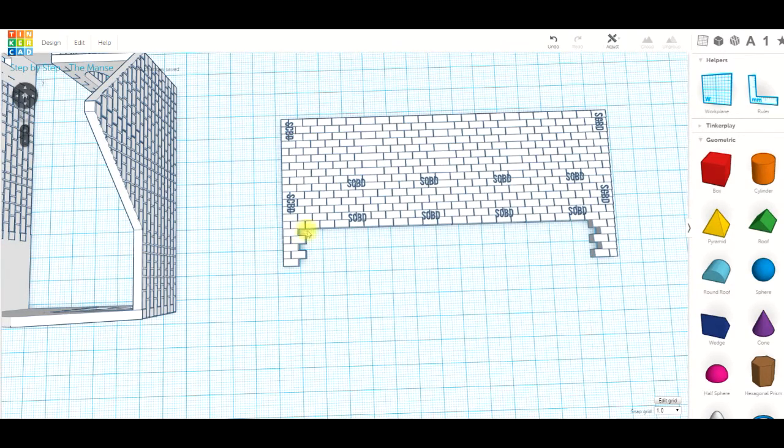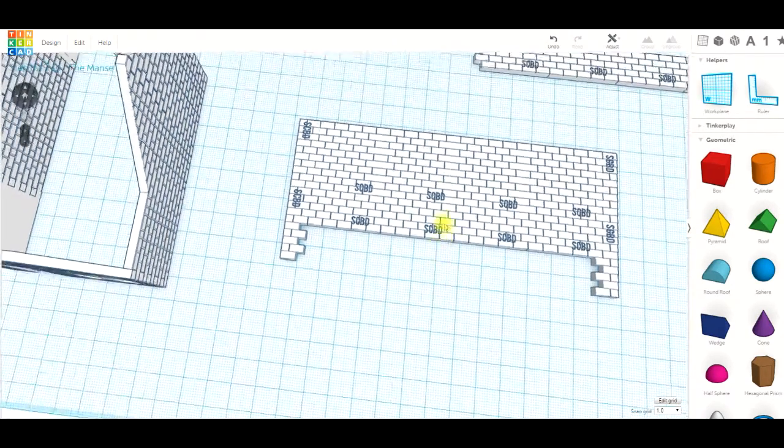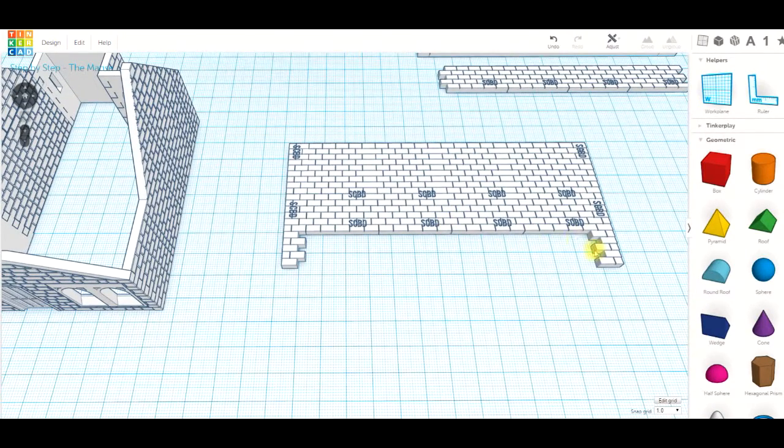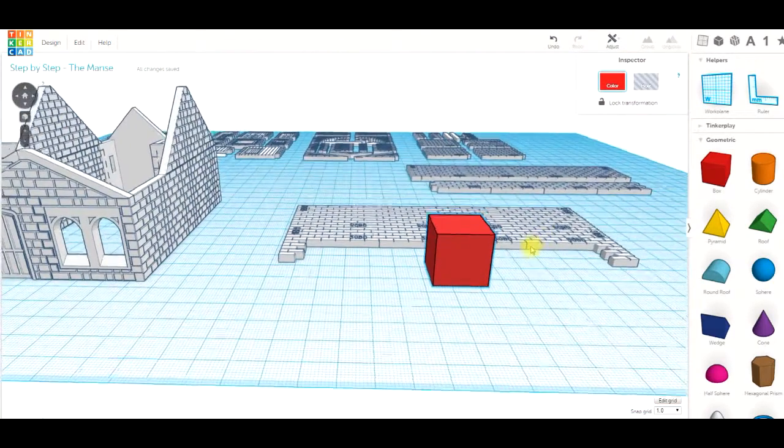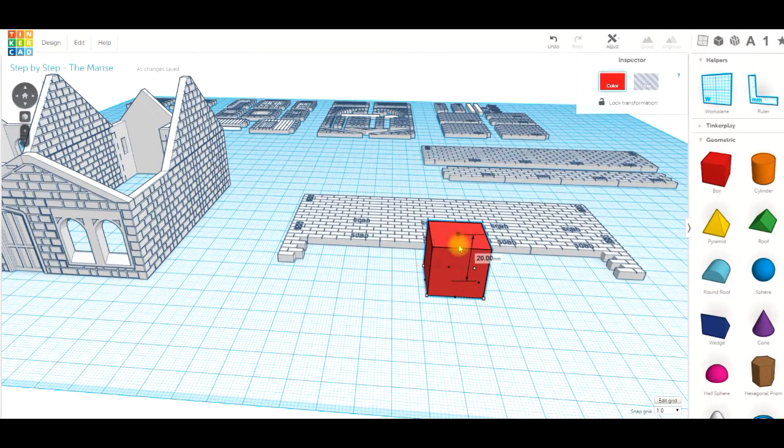Now you want to cut these pieces off, and this is a little bit of a strange tool to use, but I'm going to cover it in here. Okay, this is where we're going to use some objects here, and generally it's this box. So click the box, drag it anywhere onto your work plane and just drop it. Okay, nice and simple. I generally move that down to about 5mm by the little middle button there. The little black arrows allow me to size it sideways or lengthways. I can move this around as much as I want.